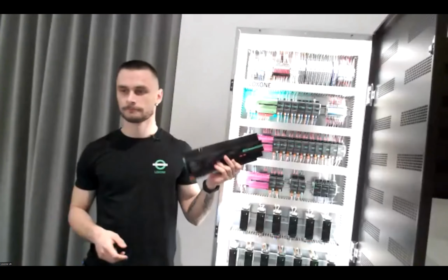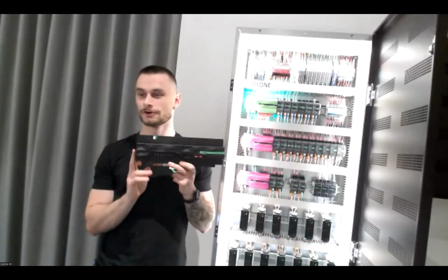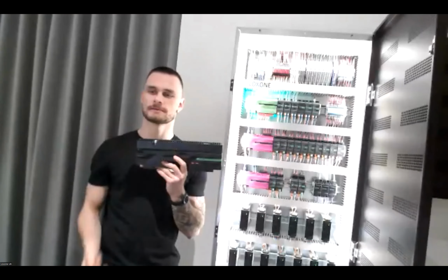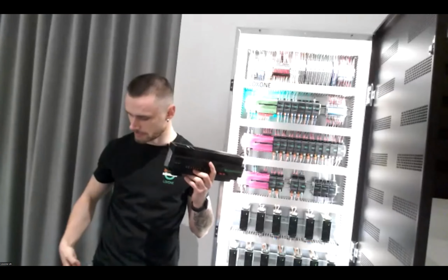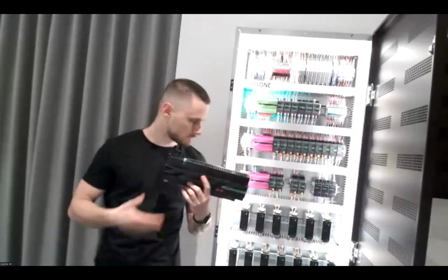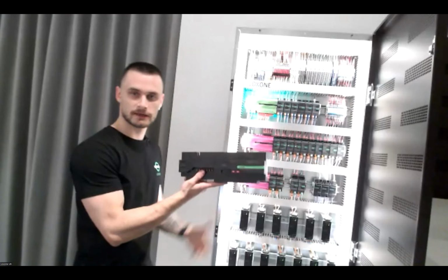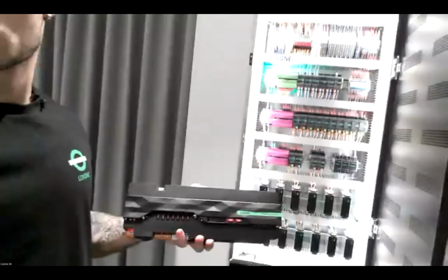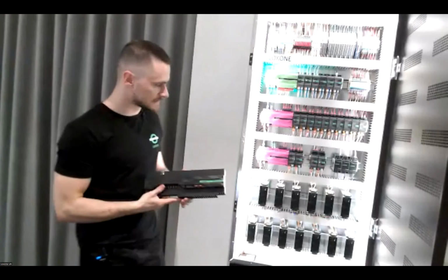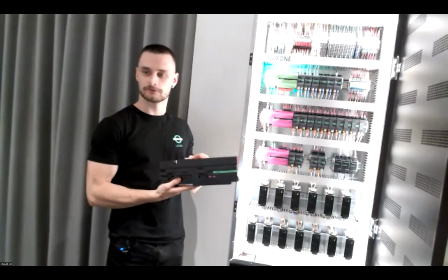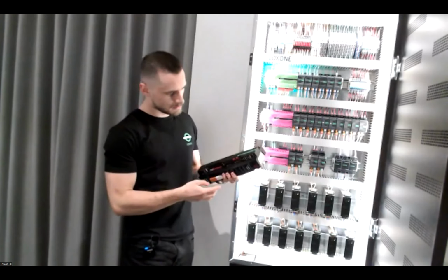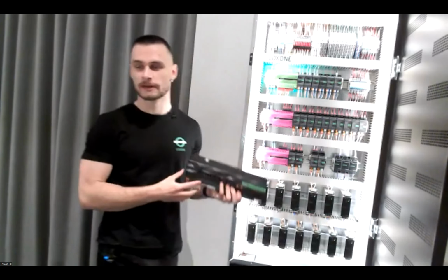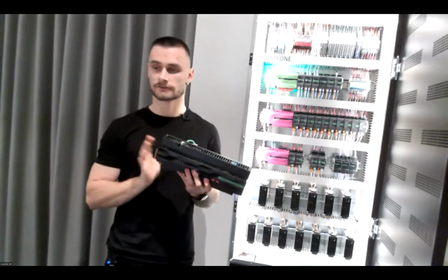So, power supply and backup, 18 breaker units of space, or for better visualization, it's 2 mini servers. So if you have 2 mini servers back to back, this is how big the device is going to be. Now, this is what actually is going to replace all of our power supplies. So instead of having 130 amps, we're just going to have 40 amps of power supplies. That is going to go most likely in the bottom if we're being lazy, or maybe we can push it all the way up to the top because of heat dissipation.